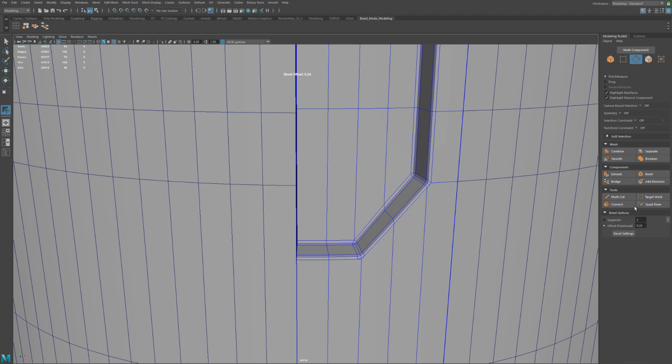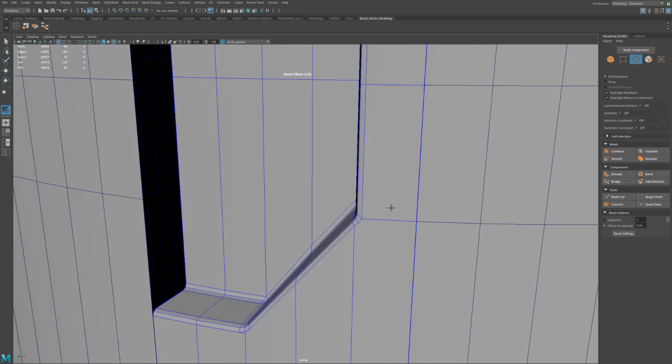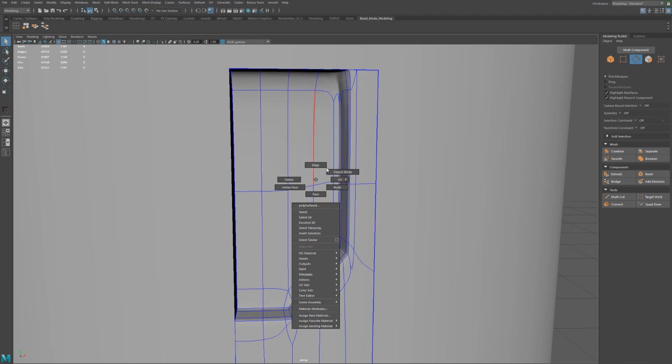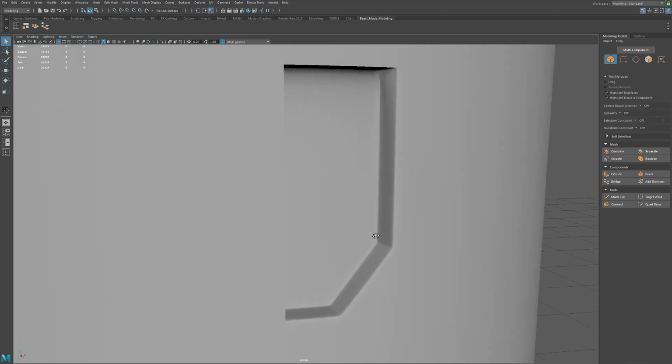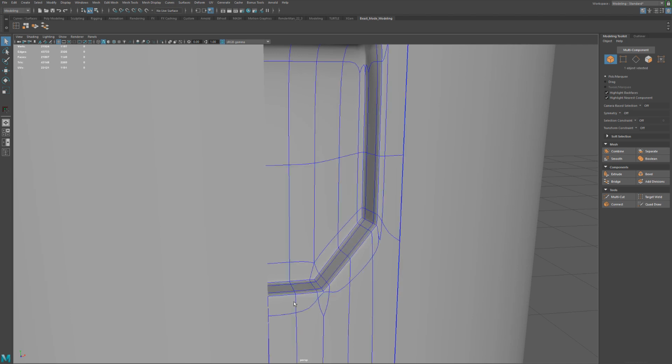And I'm using this tool here, this bevel option within the modeling toolkit. And that's going to give you these interactive options for setting up your bevels, right? So we have 3 divisions, and the nice thing about the bevel is that it'll put that on either side, right? So we don't have to manually do it. I'll hit 3, and we'll see how we're doing here, right? So this is actually not too bad, but we'll definitely get pinching. I can tell by how this is collapsing.